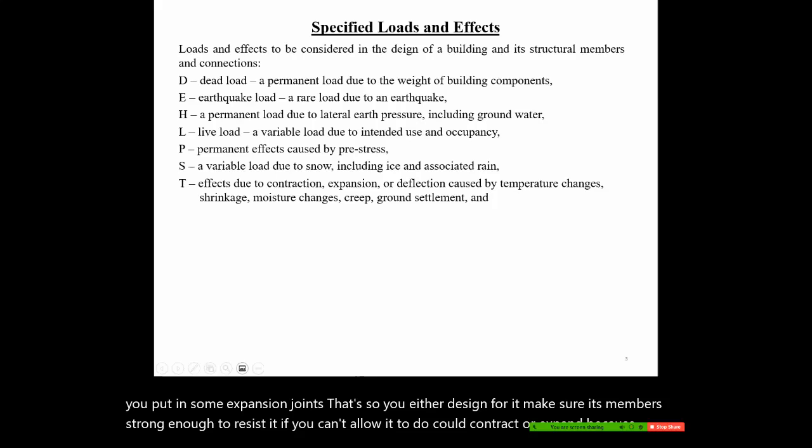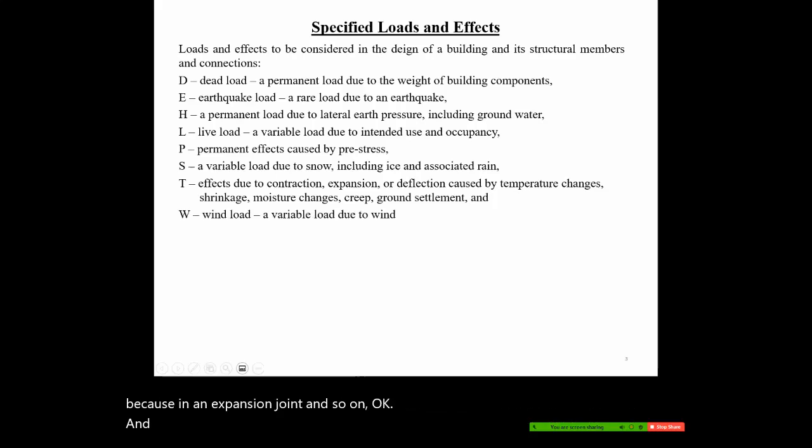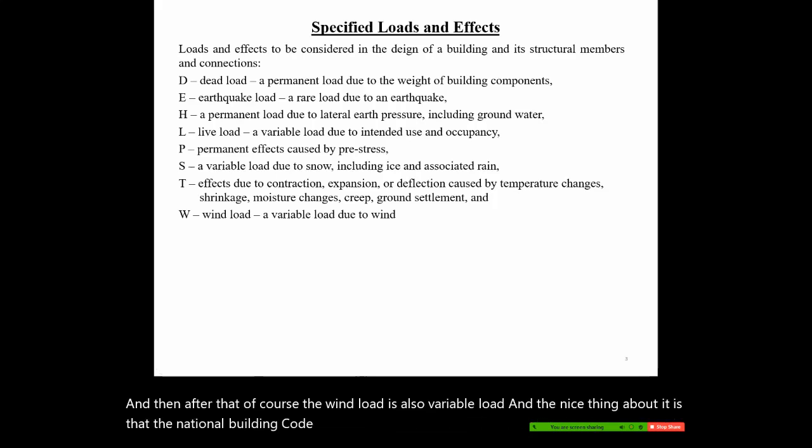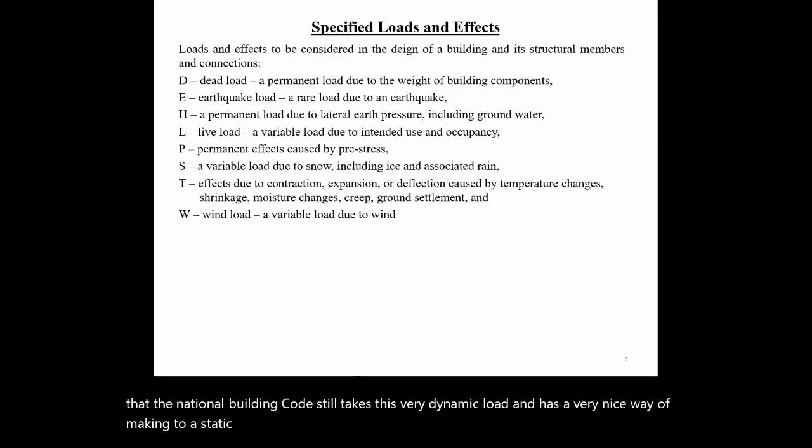And then after that, of course, the wind load is also a variable load. And the nice thing about it is that the National Building Code takes this very dynamic load and has a nice way of making it a static load. So therefore, it's easy to quantify and to do the analysis with.